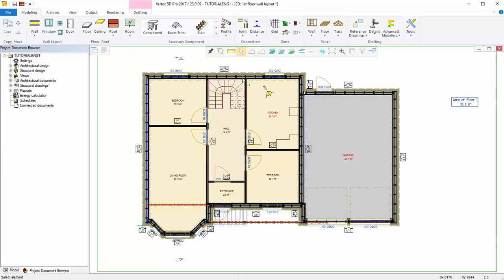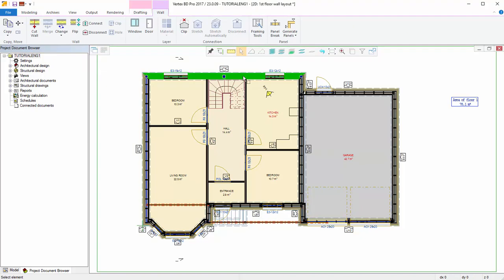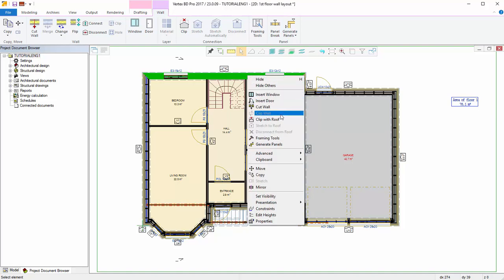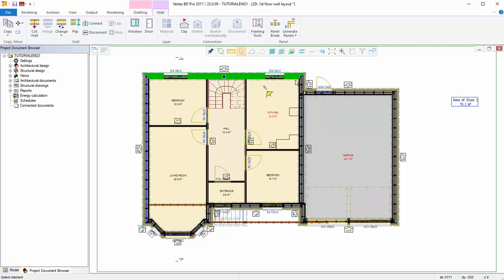When you select an individual object, its color changes and the program adds grip points to it. There opens a contextual tab which contains mainly the same functions as the object's Context-Sensitive menu. When you move the cursor close to a grip point, it changes green. If you now open the Context-Sensitive menu, there are functions related to the grip point.